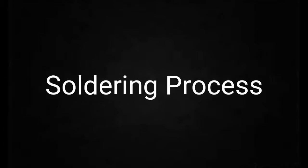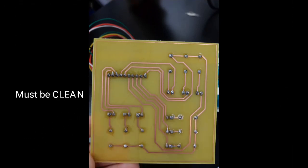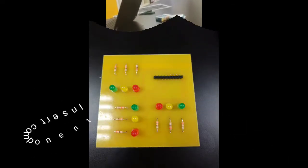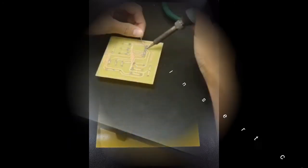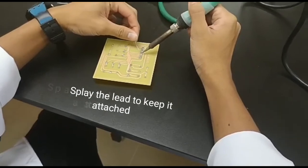Then move on to the soldering process. Firstly, the board must be clean, especially if it was not previously tinned with solder. Then, the bit of the solder iron, or the tip, is cleaned by using a wet sponge. Next, insert the components and splay the leads so that the part is held in place.